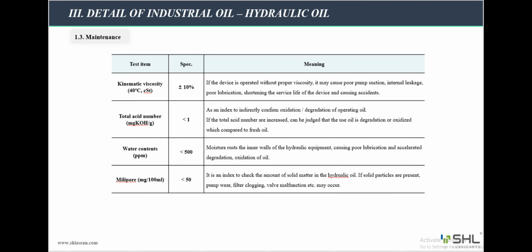The second is about total acid number, below 1 mg KOH/g, which is an index to indirectly confirm oxidation and degradation of operating oil. If the total acid number increases, it can be judged that the oil in use is degraded or oxidized, compared to fresh oil.